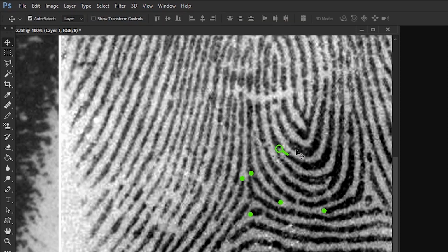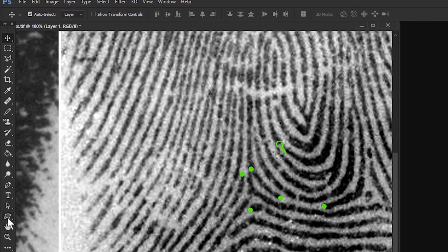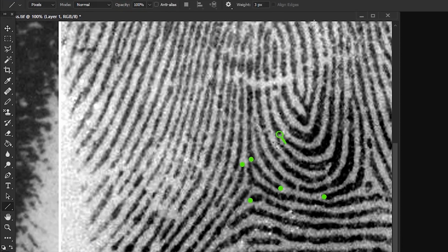If you want to change the direction of it, you have to use the Transform tool and start rotating it around and then moving it again. And it's quite cumbersome, and it really slows down your markup. So instead of that, one way around that is to use the Line tool. Now, if you get into the Line tool and come up here to these options, put an arrowhead at the start and change this concavity to -50, width and length about 600%.